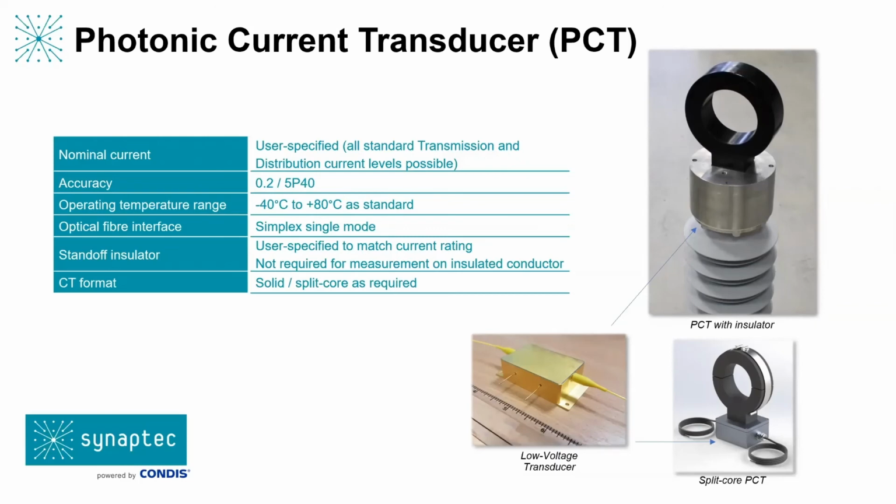So normally our application would be, as Stephen said, that we are simply providing a kind of multi-point or multi-zone faulted section identification scheme and publishing sample values to tell the protection scheme with more precision and accuracy how to respond to a fault and where that fault is contained within an electrical section. But StatNet just challenged us to go a step further and also cover the protection algorithms as well, just to prove that it can be done.